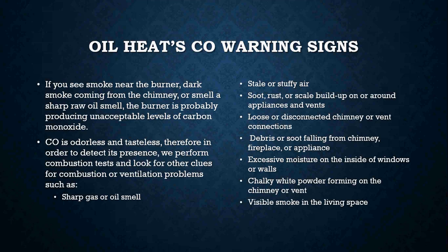Oil heat CO warning signs. If you see smoke near the burner, dark smoke coming from the chimney, or a sharp raw oil smell, the burner is probably producing unacceptable levels of carbon monoxide. When you are looking at a chimney in the dead of winter, you want to see white smoke coming out. If you see black smoke coming out the chimney, that's a telltale sign that it is not operating correctly.